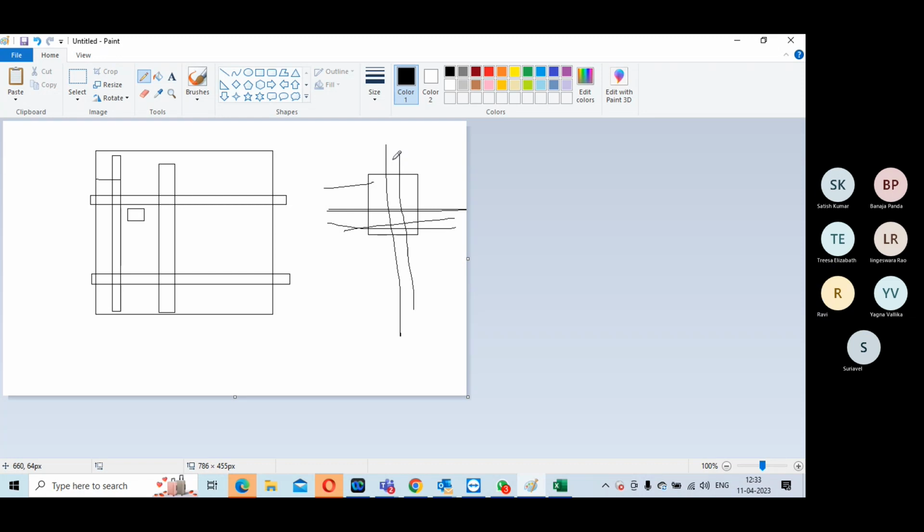You understood? Okay. So input power is this one, output power is this. Then when I give a signal that you sleep or shut off, it turns these things off and switches it off. The problem is once you have switched it off and suddenly you are turning on everything. That means all the logic is getting power at a time. That's what is called rush current, and that is going to destroy.